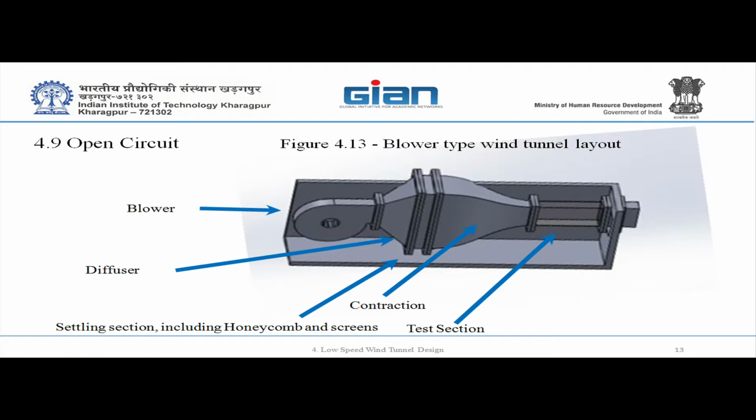So that's why the sections for the turning vanes are the largest in the neighborhood. There is no other purpose for that. You don't just diffuse the flow to have fun. And then you diffuse it here to get to the settling chamber with low velocity.